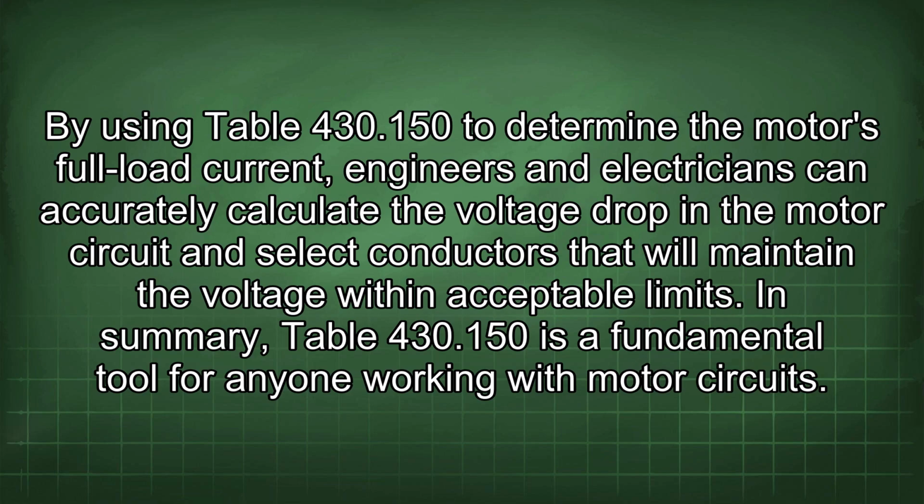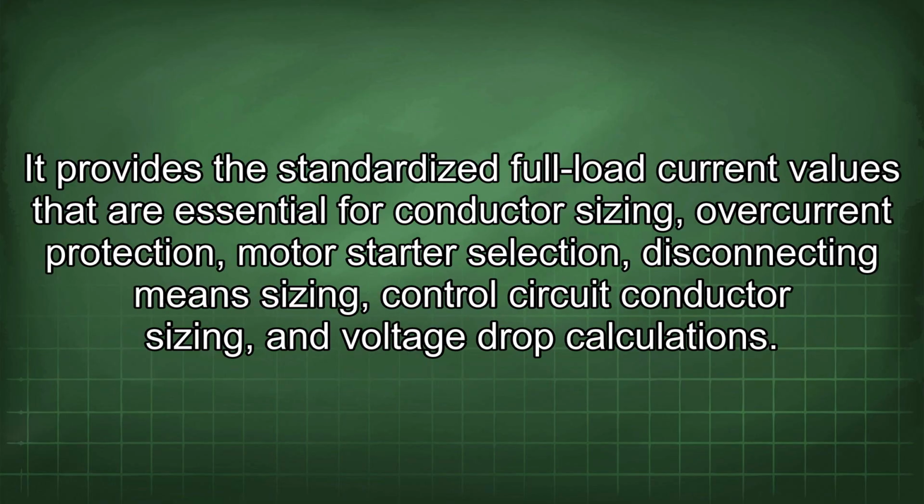In summary, Table 430.150 is a fundamental tool for anyone working with motor circuits. It provides standardized full load current values that are essential for conductor sizing, overcurrent protection, motor starter selection, disconnecting means sizing, control circuit conductor sizing, and voltage drop calculations.